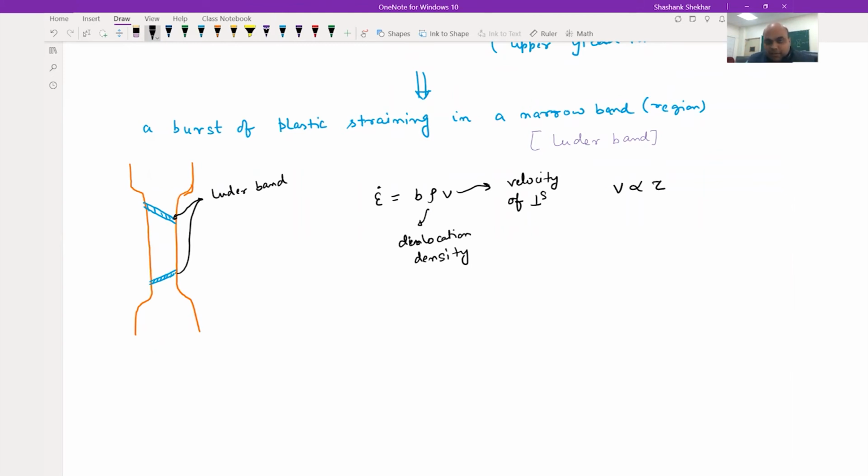Okay, now remember, whenever we do tensile test, we always try to do it at a constant strain rate. Okay, so we apply constant strain rate, say 10 to the power minus 3 per second, 10 to the power minus 4 per second, something like that. Okay, so constant strain rate is on the left side. So we try to maintain this term epsilon naught as constant. Okay, b is also constant.